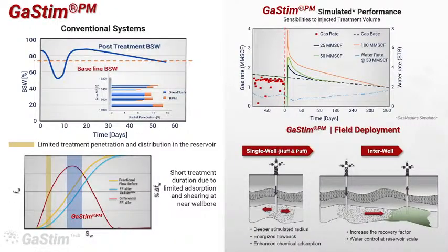When you see the results of conventional systems, you will see a very brief reduction in the BSW percentage, and then you go back to the baseline BSW that you were seeing before. So the durabilities are very limited, because the penetration of those liquid-based treatments is very low, and the volumetrics that you're managing are not that efficient.